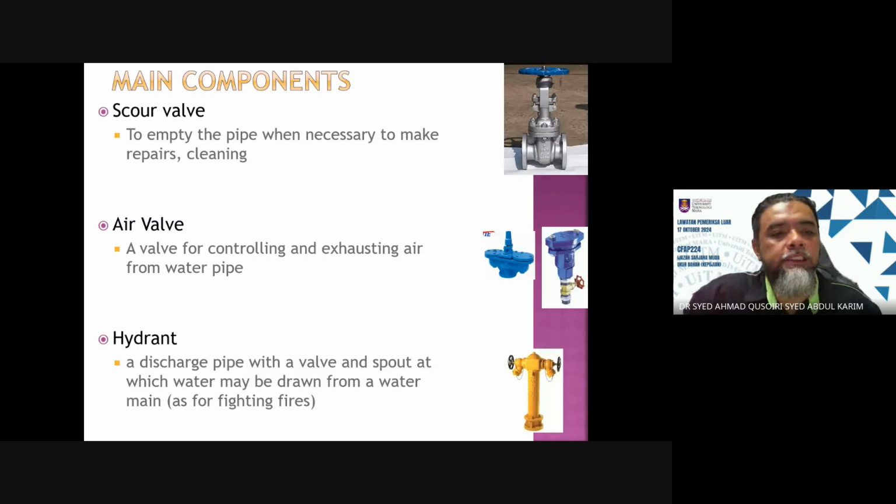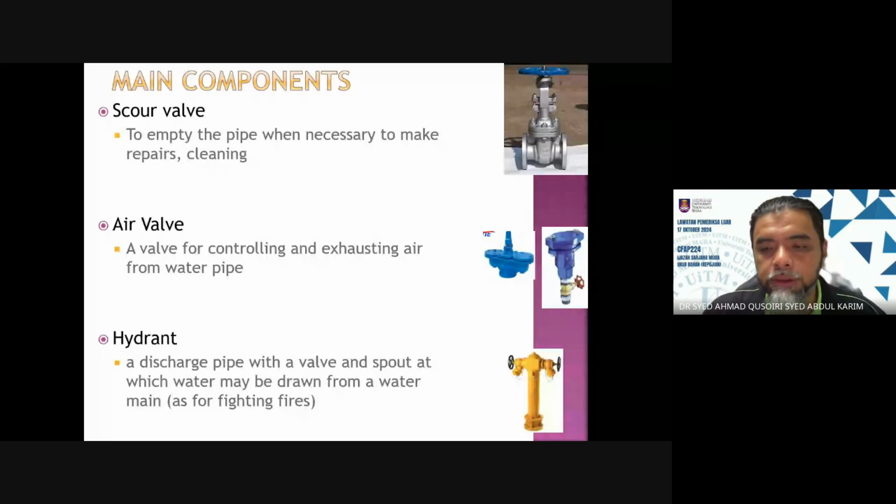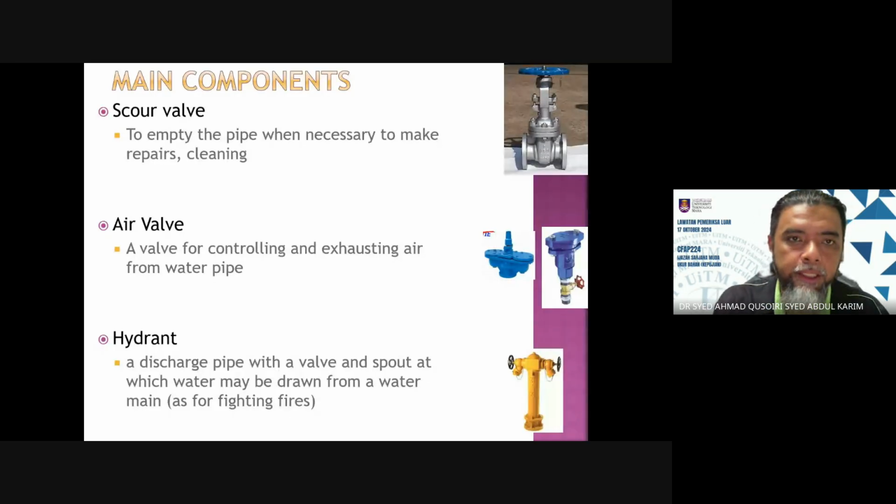Okay, and then the scour valve, and then we have the air valve. So in these pipes, it's not just water that flows, but sometimes air bubbles might also flow together with the water. So these air bubbles need to be ejected from the pipes, okay, because we do not want any issues in terms of pressure and things like that.